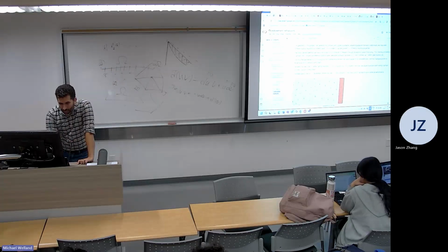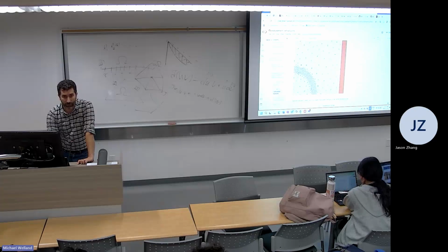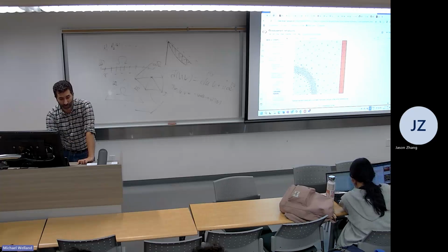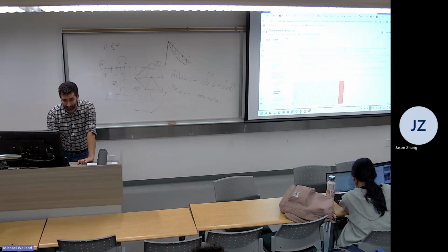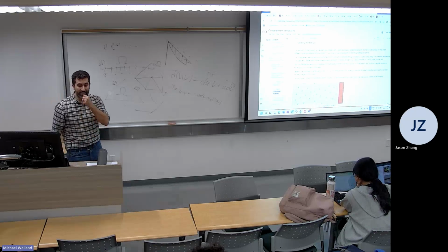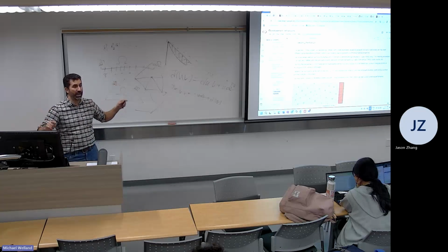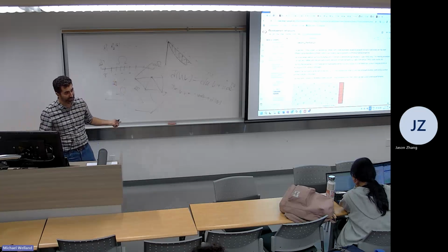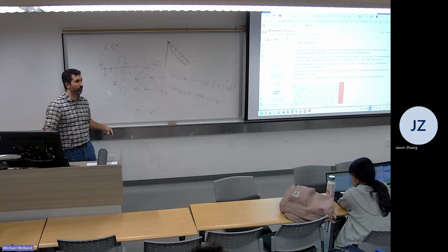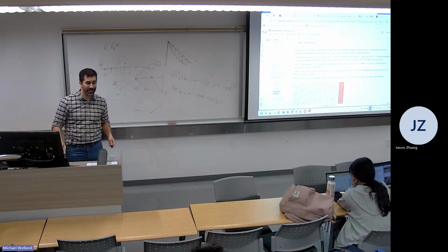The nice thing about this is that we can do funny business. We can have a very refined mesh in here where lots of stuff is going on and then expand our triangles out. You'll notice there aren't any hanging nodes anywhere, hanging vertices. And yet we can still have larger elements out here. Different material properties, not a problem. What we've done is we've partitioned the geometry into a finite set of elements. Finite element method. That's one of the interpretations of what finite element is referring to. There is another one that has to do with the shape functions.